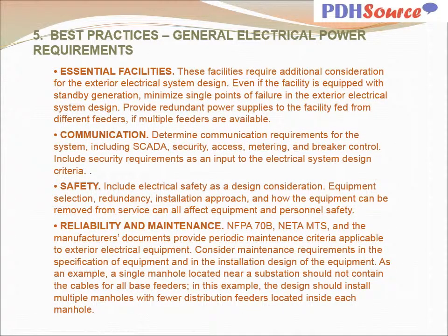With regard to essential facilities, these facilities require additional consideration for the exterior electrical system design. Even if the facility is equipped with standby generation, minimize single points of failure in the exterior electrical system design. Provide redundant power supplies to the facility fed from different feeders if multiple feeders are available.